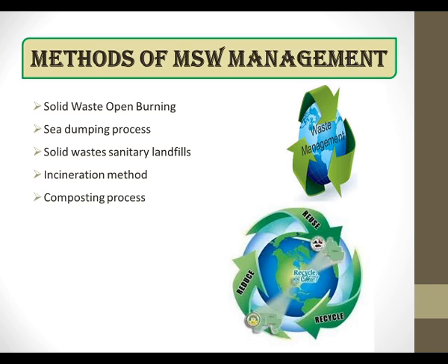The next process is the composting process. It is similar to sanitary landfill and it is popular in developing countries. Disposable organic matter is separated and composted in this procedure. Two methods are used in this process: open windrow composting and mechanical composting. The next one is disposal by ploughing into fields. Disposal by ploughing into fields is not commonly used. These disposals are not environment friendly in general.